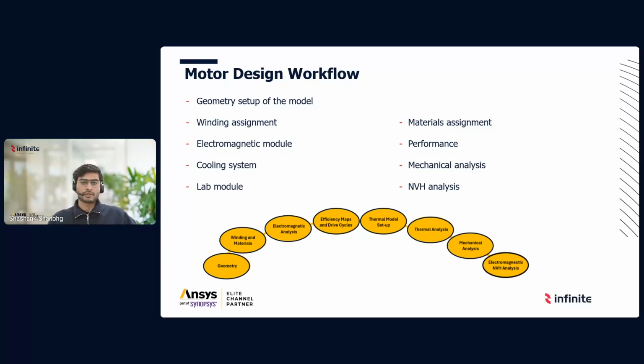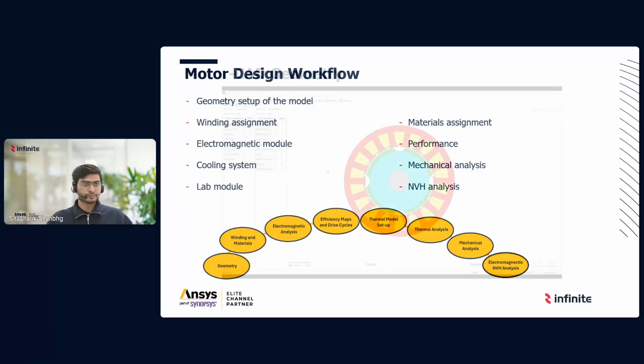You can check for how the machine would perform. And finally, you can also do the NVH analysis. You can check for the different vibrations, how the sound from the motor is. Yeah. And once you follow this workflow, it will be really easy for you to have a complete multiphysics design, and you'll be ready to go with your motor.